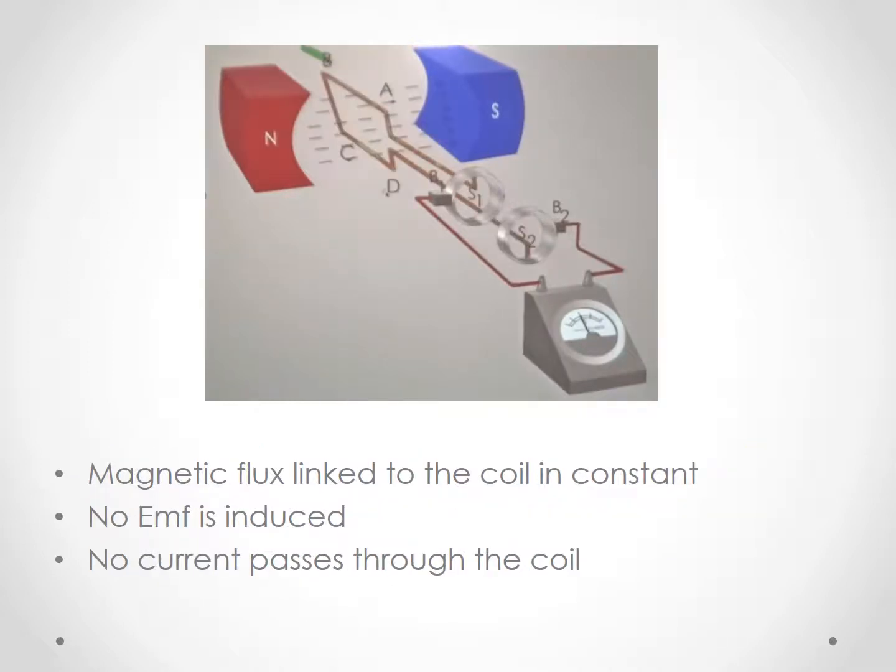When we continue to rotate the generator, there is a point where the coil returns to the original position where there are 6 lines passing through the coil. The only difference here is that now AB is on top and CD is at the bottom, unlike in the beginning when CD was on top and AB was below.